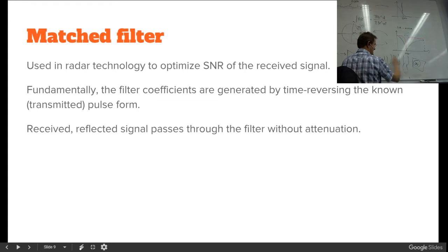And your radar sends that pulse. And in order to measure the distance, it's time of flight correlation which is done. There are all sorts of different signals around it, but on the receiver end, you can match the measured data with the measured pulse. You will basically make a perfect filter.